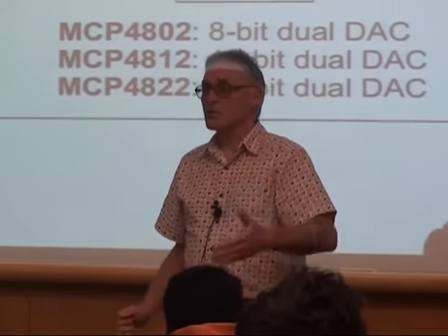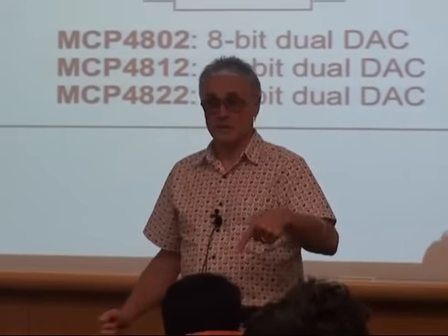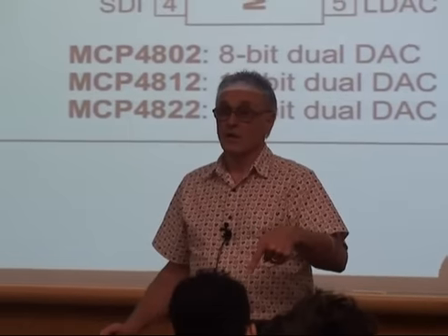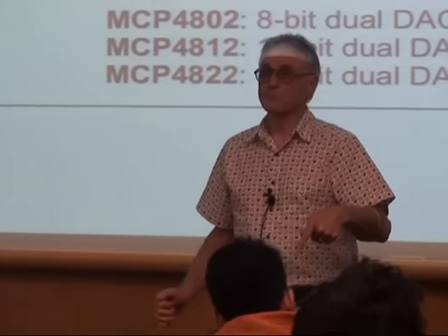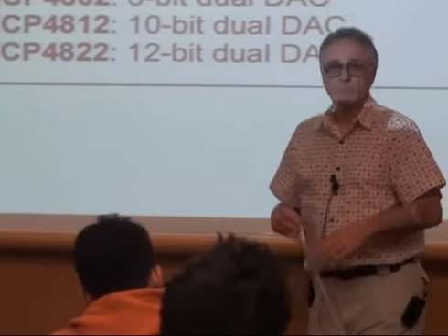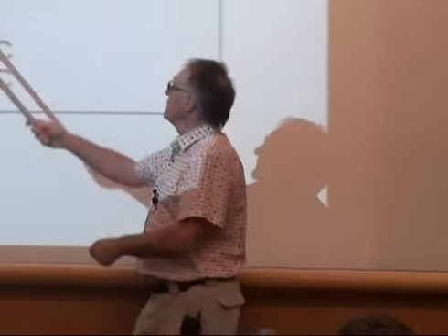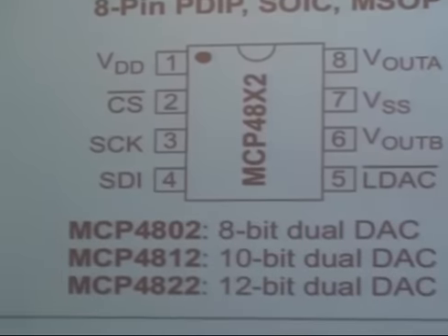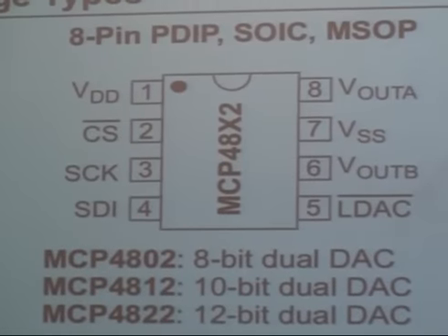You have to short out that inductance with a capacitance, or the chip will fail. So always, with fast logic, or an op amp, or any integrated circuit you put on the board, put a 0.1 between VDD and VSS and save yourself some tears.